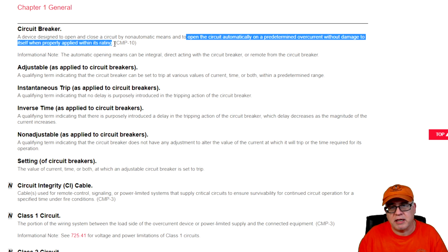So in a short circuit condition, you have a phase to phase short, a lot of energy is transmitted, and it allows the breaker to operate. In a ground fault condition, you take any phase conductor, it faults out to the effective ground fault current path, then it causes a big explosion at that point of connection, that fault point, and it allows the overcurrent device to function, which in this case was a circuit breaker.